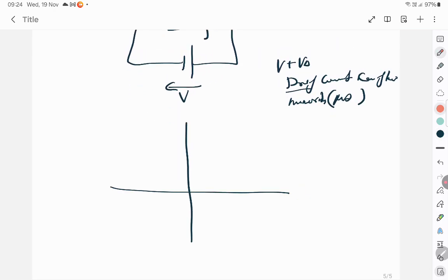In the forward, this is forward bias, positive voltage, this is negative voltage. This is milliamps current, this is microamps current. You must ensure that the graph is touching the x-axis for some increase in applied voltage. I told you, as you keep on increasing, it has to overcome the barrier voltage, when the current starts steeply rising. And this is called the knee voltage